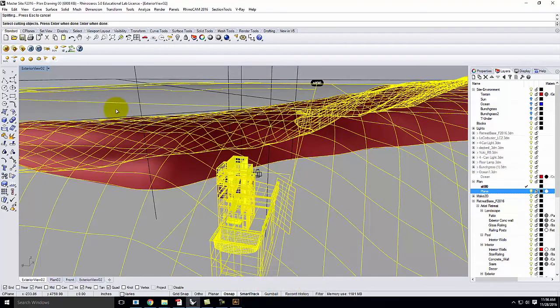Okay, remember the split process can take a while. Because I exploded the blocks, it should go fairly fast. There will, of course, be some failures in the process. Those are generally objects that are all below the plane and don't intersect with the big plane. So it's normal to see a few failures, and we'll confirm it in just a second when it's done. Okay? So once again, I'll let this run for 3 or 4 minutes. It's probably going to take that long, and then I'll call you back and talk to you about the next part of it.